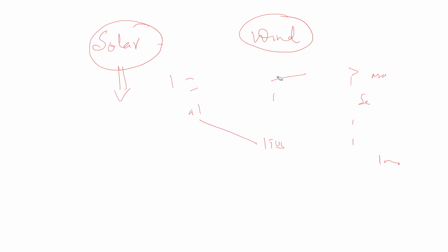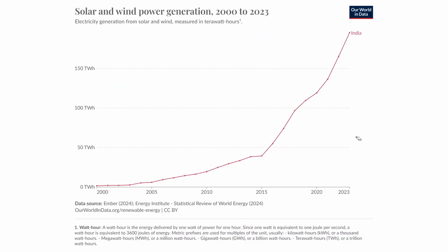And the nature of the data, is it analog or digital, sir? It is generally digitalized. In smart metering, it is generally digital. So the analog to digital conversion, is it happening in the IEDs or the RTUs, sir? Actually, it will be done at the data concentrator, where the data is taken up, and at the master station. At that point the data is digitalized, because as a human you cannot analyze analog data. There will be software in which the data goes and shows the trend. If there are any outages, based on that analysis the operator can control those things.